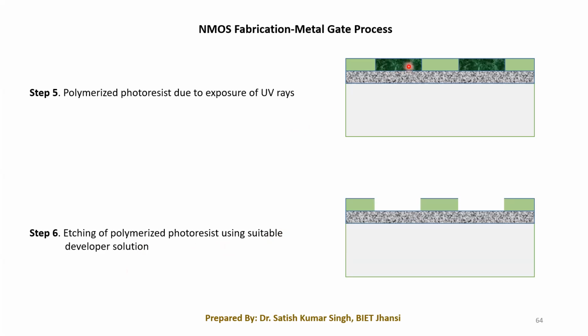Fine. So what we have to do is put this entire wafer into a particular developer solution, and because this has already become polymerized or softened, it will be dissolved into that solution, and then this area will be opened. Fine. So now we have opened this particular area. Once this is opened, this window is opened over here.